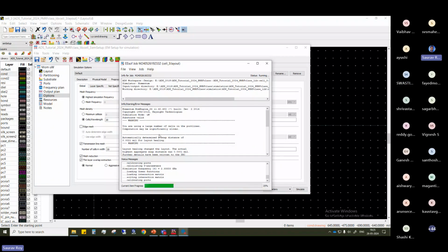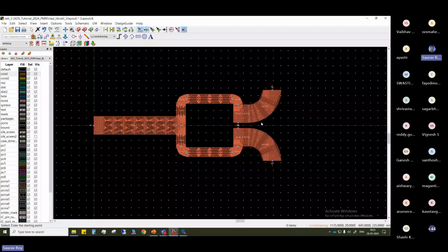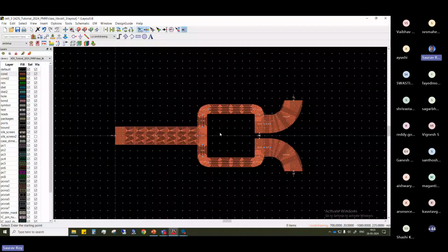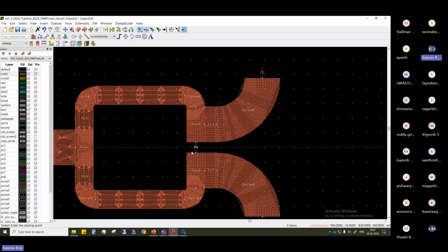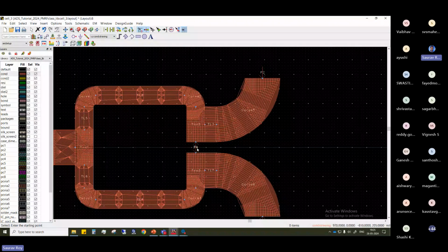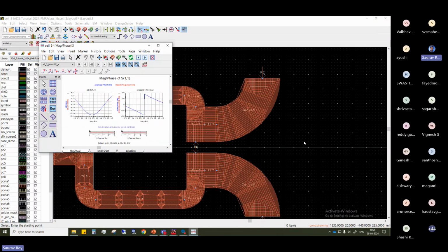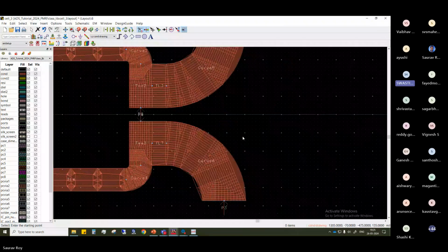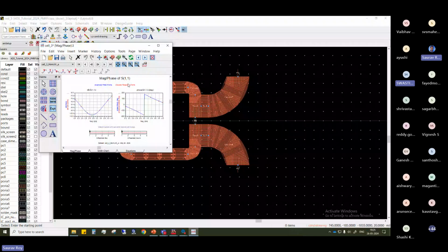So yeah, that is also crucial. One way you can do is create this gap here between the ports such that it will be as given in the datasheet. Otherwise, you can take a pad also here. Those microstrip pad lines are also available in the components, specific to pads. That is also available.